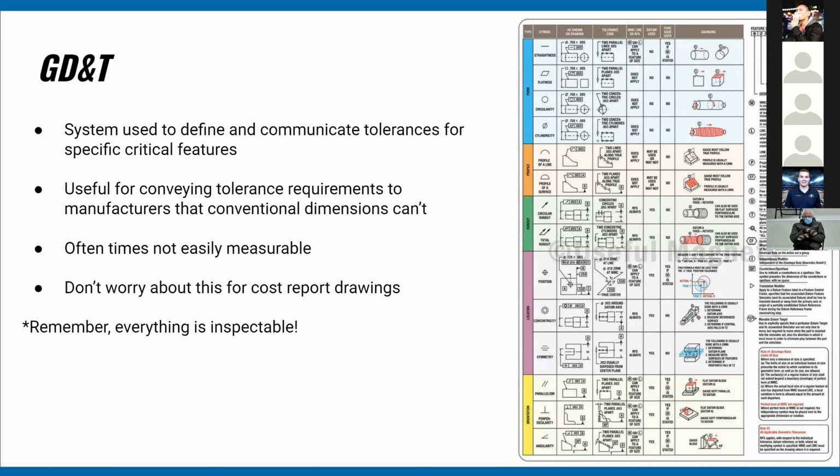Some of those are features like flatness, which is really useful for defining a surface that needs a gasket or a sealing surface. That's super important. Or you can have a positional, locational tolerance that you need to define, like a hole pattern, because you've got a part that has a specific tolerance that needs to mate up correctly.